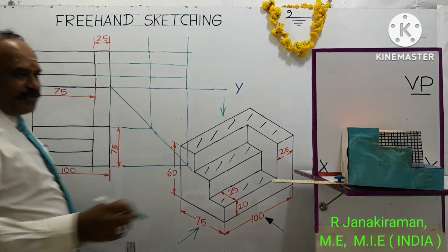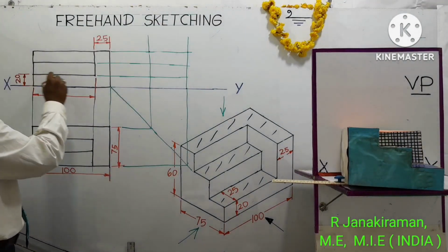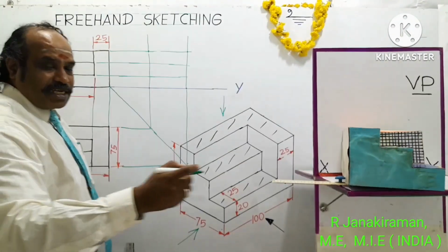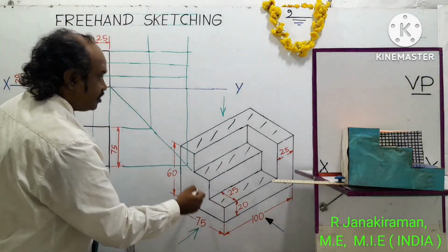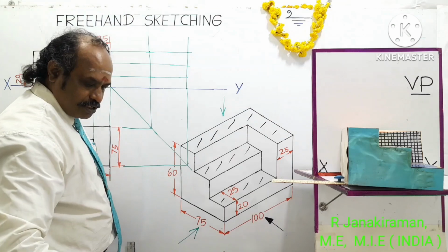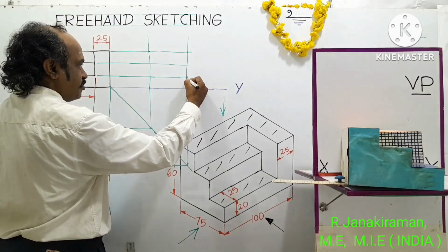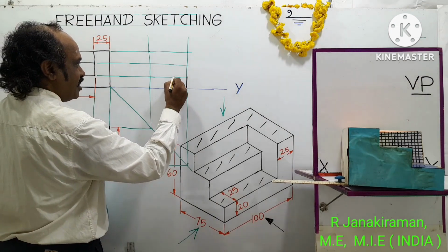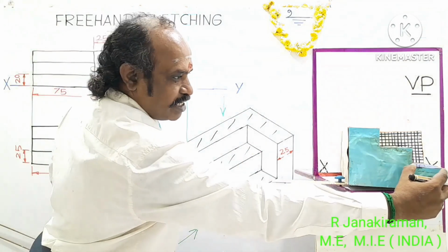So now you can find the step 1 height. It's already previously drawn in the front view, it's traced, and the horizontal distance of the step 1 is 25 mm. This is step 1 height. The 25 is traced from here, front view, to the side view. Then you draw one horizontal line equal to 25. This corresponds to this length.